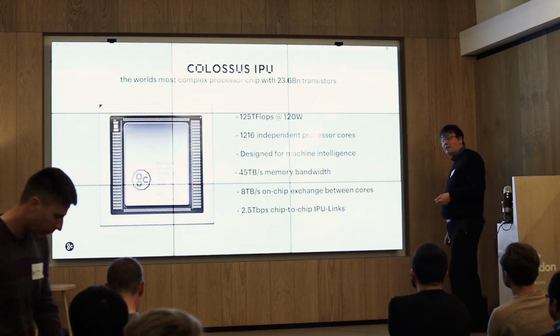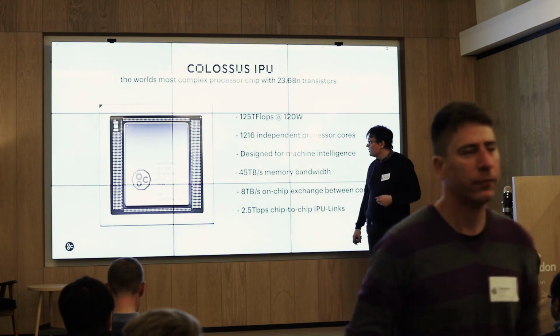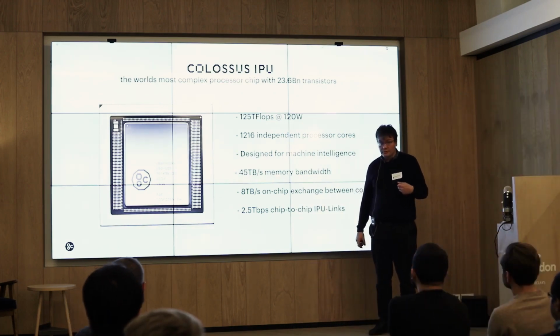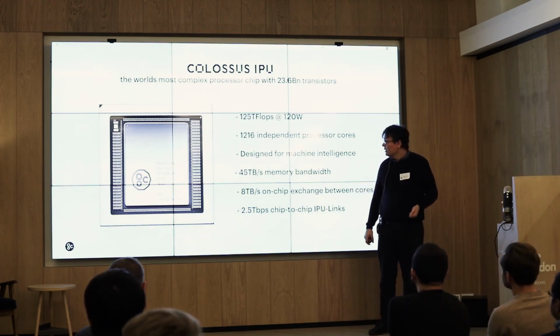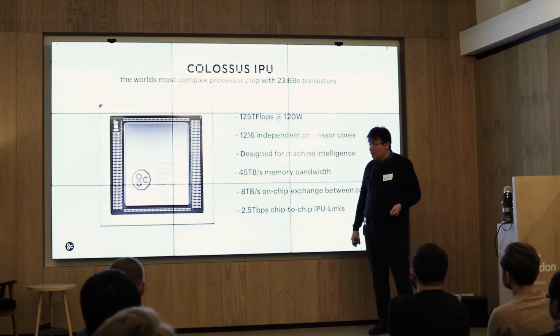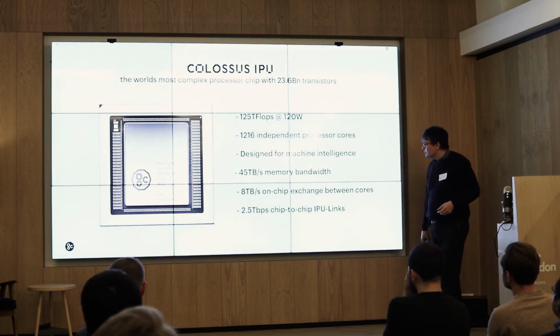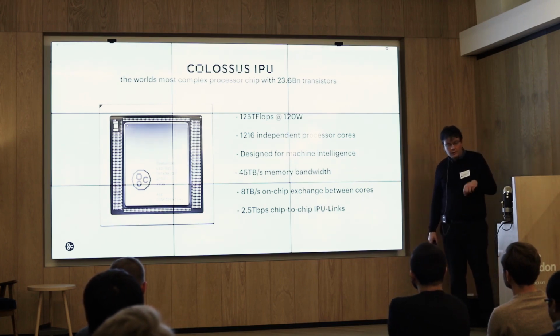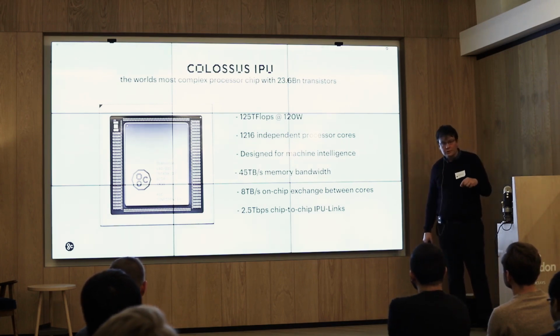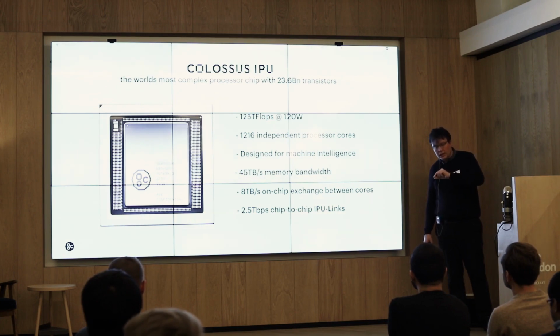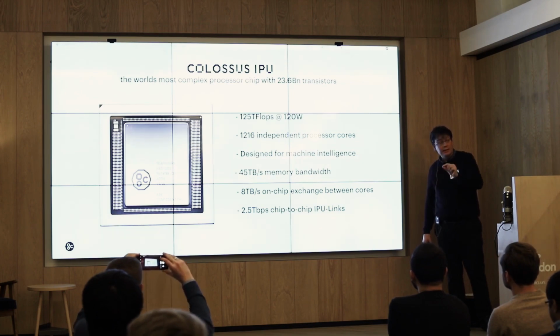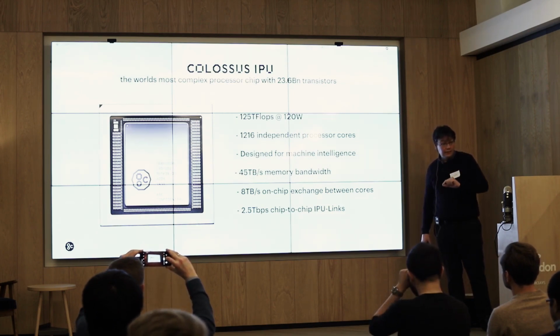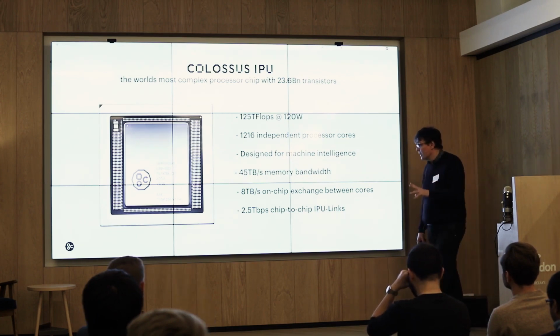It is a highly parallel big chip. It's got 125 teraflops of floating point performance, so it's a very highly spec'd compute chip. That's half precision floating point. And it's got a lot of on-chip memory and a lot of on-chip bandwidth. This allows you to focus on not just getting the high compute, which you see that you need, but also the innovative algorithmic changes, by being able to swap around data in very different patterns in a very fast way. So that's what we made.